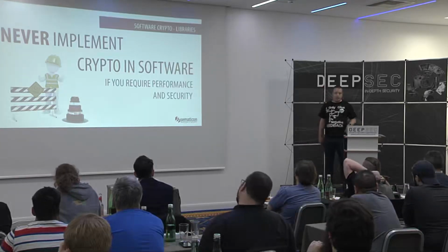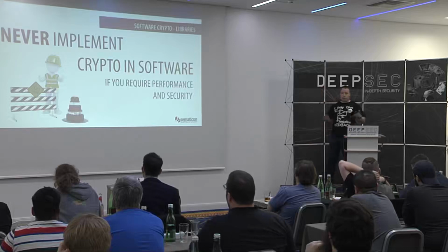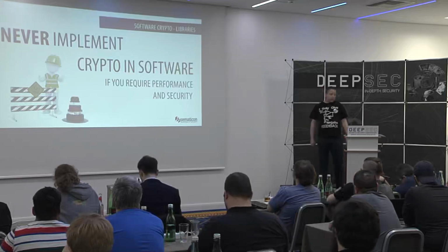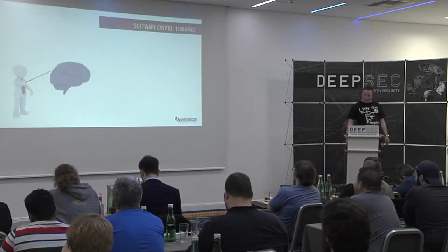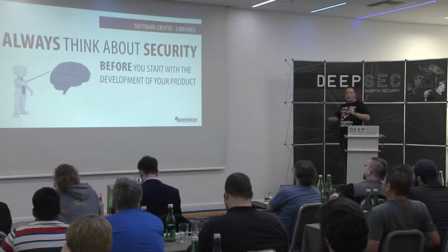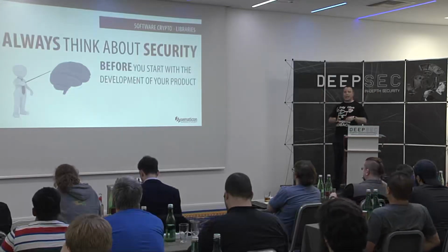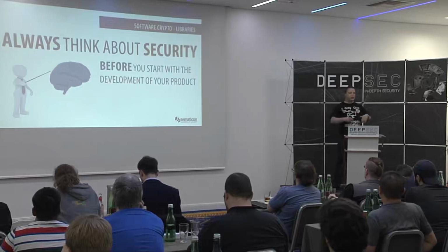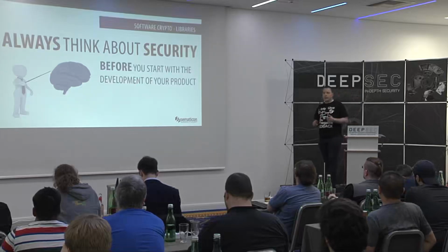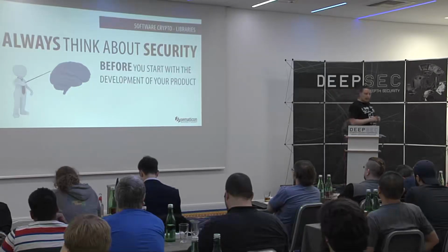So the best thing is, let's do it outside, in a secure element of your choice, to make sure that keys lie in hardware. And please think about security before you start the project, because that means you have to add additional hardware in your design, or you have to put an HSM in your data center before you start. Doing it afterwards doesn't really make sense.